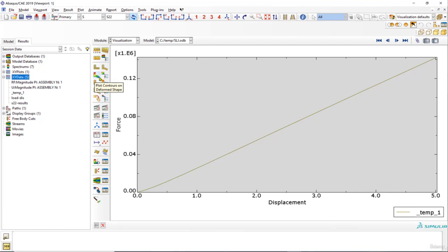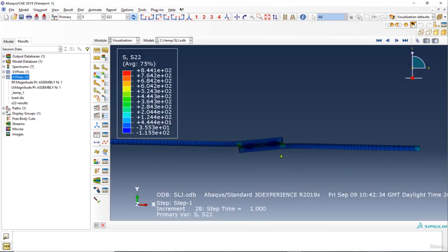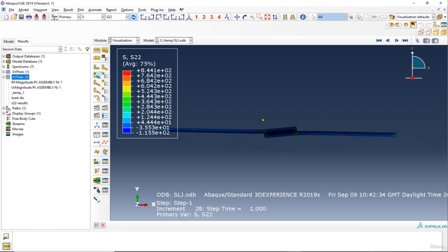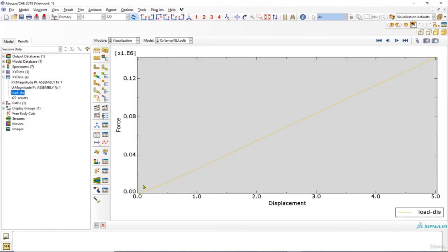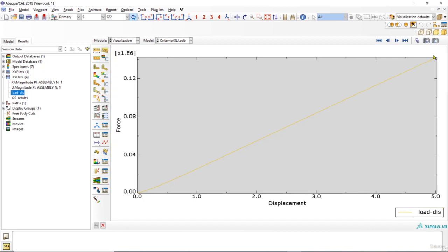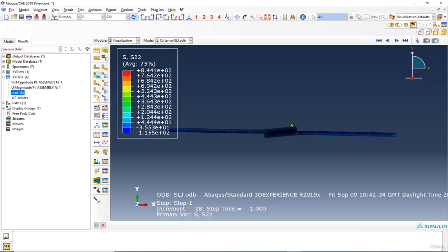our joint. Normally this type of joint, especially with a brittle adhesive, is not going to deform 5 millimeters. So 5 millimeters is too much. But if we had any sort of failure criteria, this joint would fail after less than a millimeter displacement, normally 0.7, 0.84 for brittle adhesives. But because we don't have that failure criteria, we only have a linear one, which starts from 0 and goes linearly up. So it doesn't really matter what displacement you apply, this force is going to go up without any sort of failure until you put that failure criteria in your simulation.